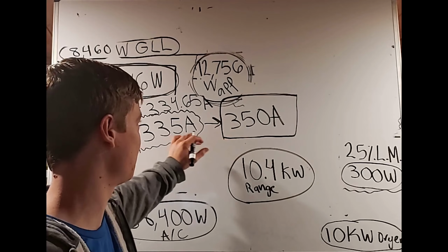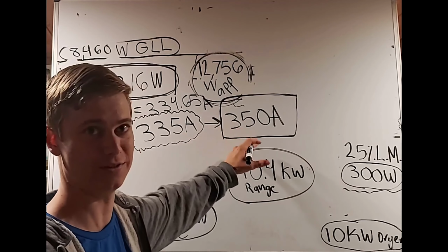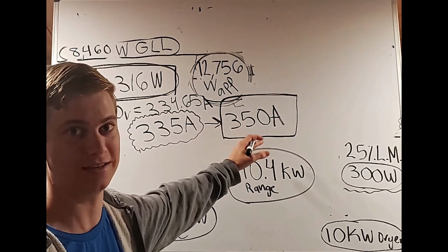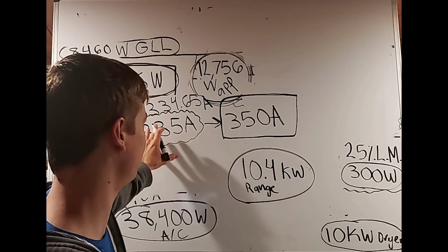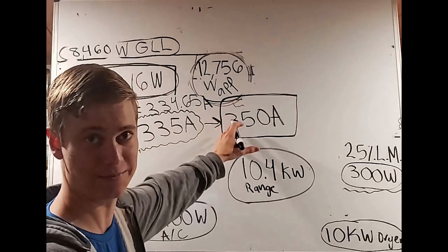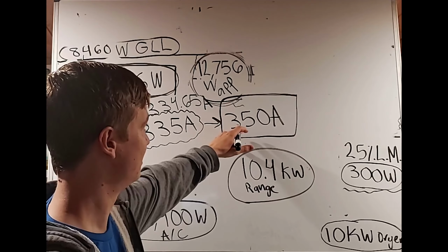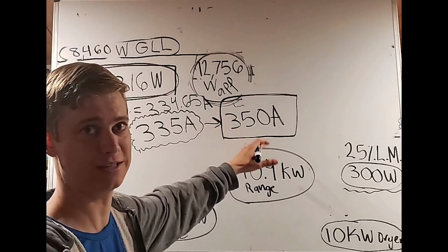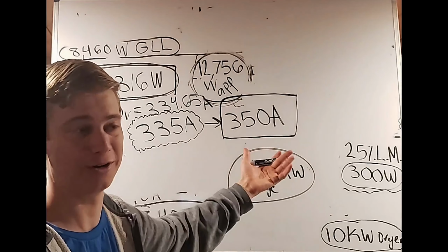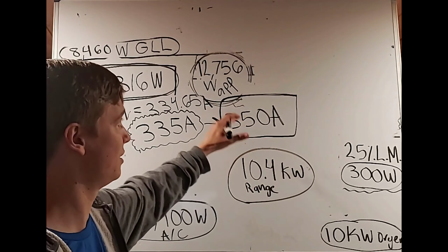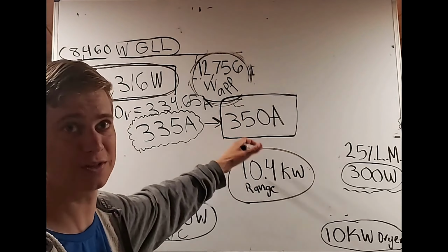Okay, so we have our number for our overcurrent protection device. In other words, the question was asking for the minimum overcurrent protection device. After solving all this, rounding up, and sizing up to the next circuit breaker, now we know that overcurrent protection device. If you don't know what that means, an overcurrent protection device is basically any breaker. So this is going to be our main breaker, 350 amps, or in other words, our service.